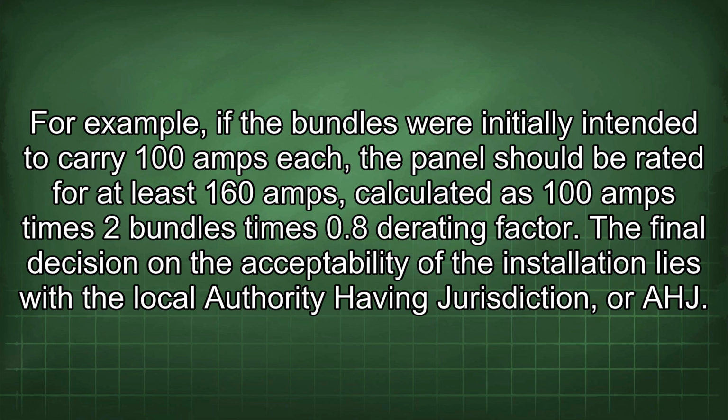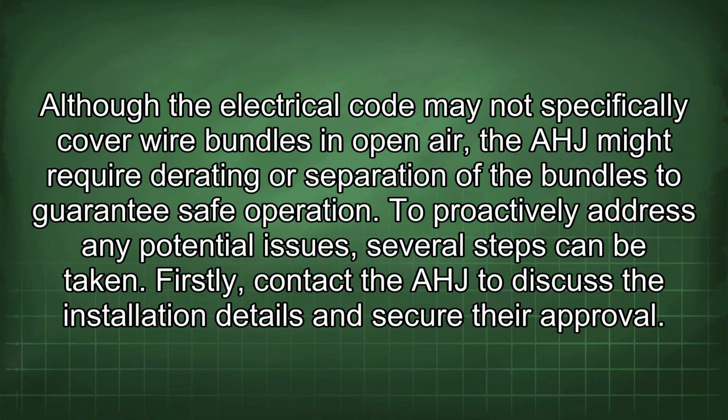The final decision on the acceptability of the installation lies with the local authority having jurisdiction, or AHJ. Although the electrical code may not specifically cover wire bundles in open air, the AHJ might require derating or separation of the bundles to guarantee safe operation.